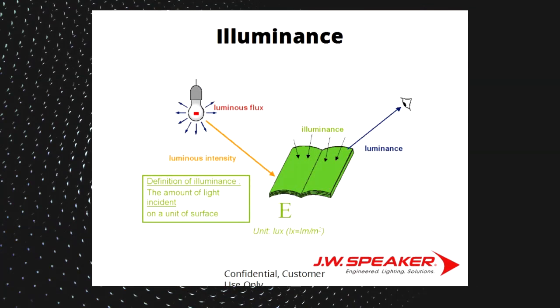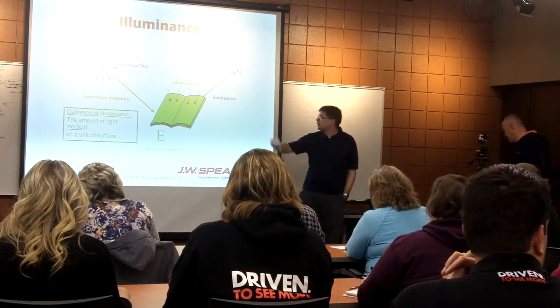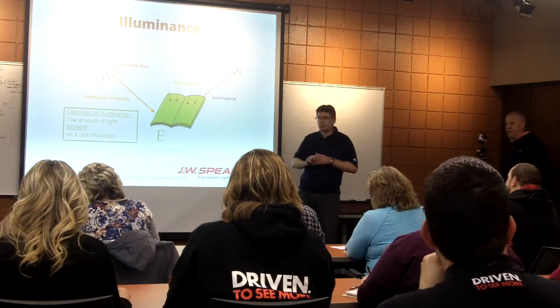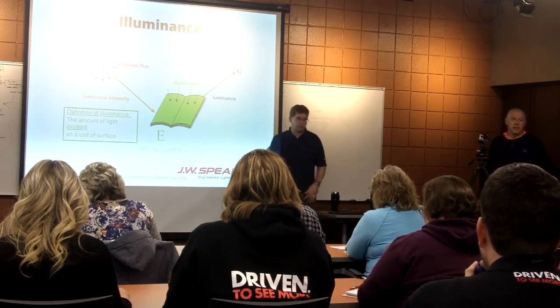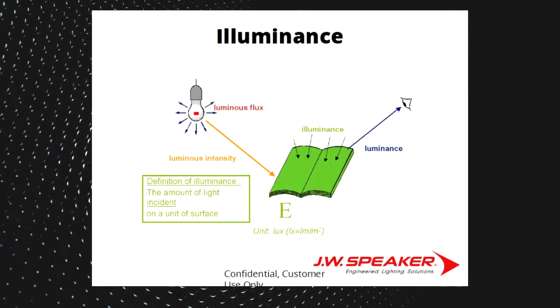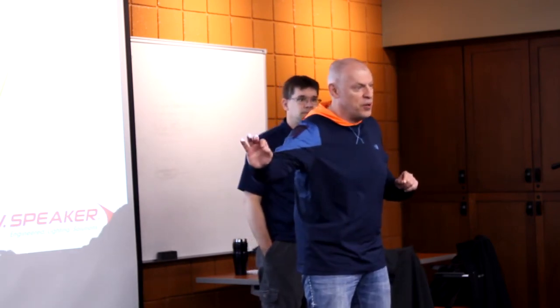So our next term is illuminance, and that is the amount of light on the surface. We started with our source emitting all that total light. There's light going in a direction. Now we're on the surface. So the light incident on the surface is measured in lux. That's the distinguishing difference. Again, directional is candela. So candela, remember, wherever we slice that, it's the same value.